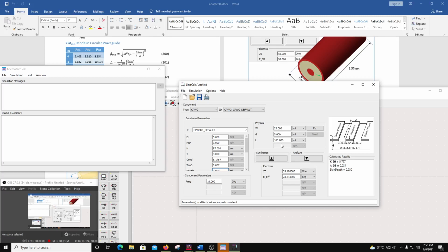Now in this case, again it is root of L over C only for a lossless line, but L and C can independently be controlled here. In microstrip line, it was just the height of the substrate which was fixed, so you could not control C independent of L. Now in this case, there is a coplanar ground, and this gap is much smaller than the height of the substrate, right? So you are able to design a coplanar waveguide with a certain width.